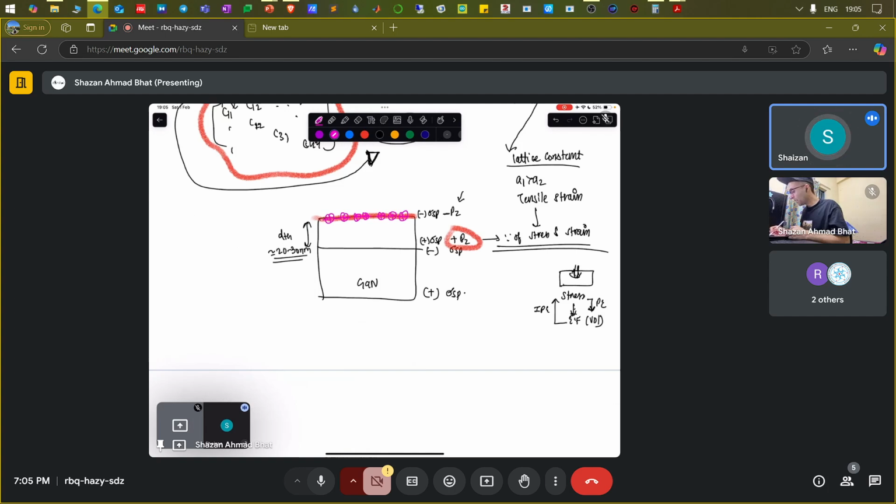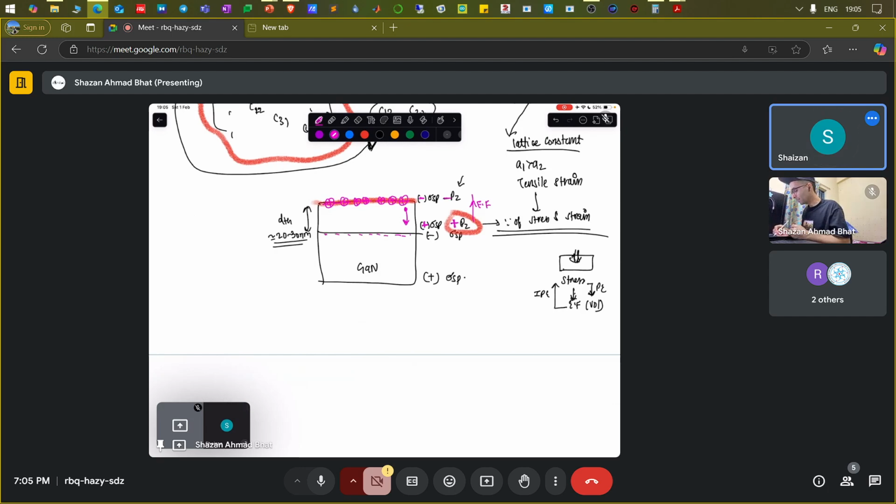Again, because you see that the electric field gets set up in this direction, because you have positive, positive, negative, negative, so the electric field goes from positive to negative, and the electron will like to flow in the opposite direction to that of the field. So what happens is when the electrons come away from these surface states, they settle here. This is AlGaN. And it's a very interesting phenomenon that happens. They settle at this particular location. And when you draw the band diagram, you will see why they settle at this position, why they don't move further into the gallium nitride.